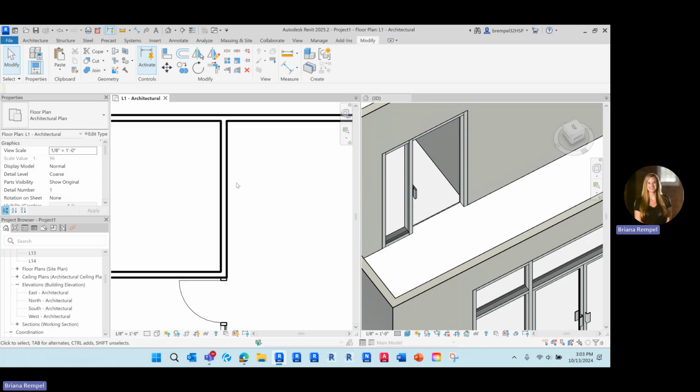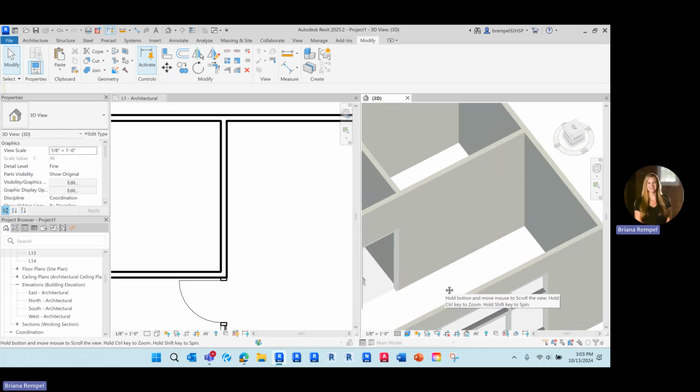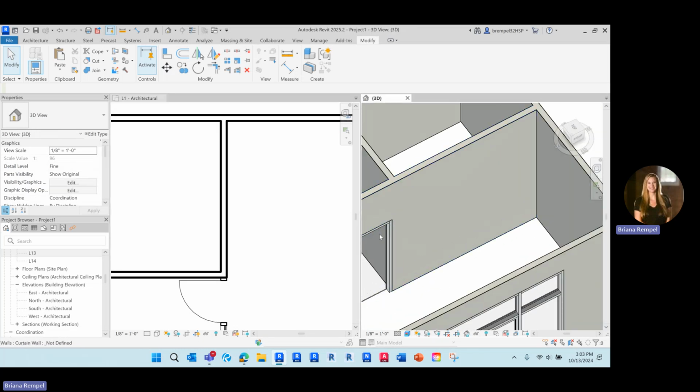All right, last one here, interior demountable partition. If you're not familiar with these, I do suggest looking up manufacturers for that. DIRTT, D-I-R-T-T, is a good one. All of your major office systems furnitures, I believe, have them, such as All Steel, Herman Miller, Knoll. They have probably some version of them as well. So these typically do go floor to ceiling, and the reason for using them is that they can be disassembled and reassembled or relocated and reconfigured throughout the space.